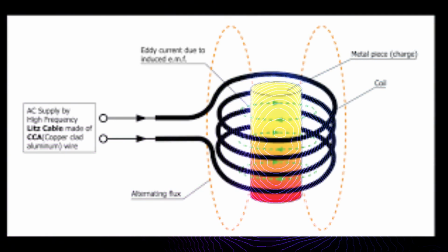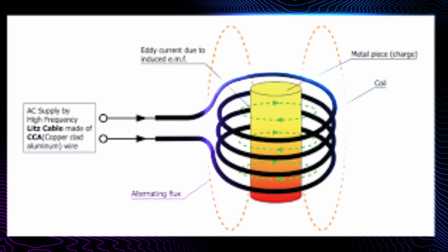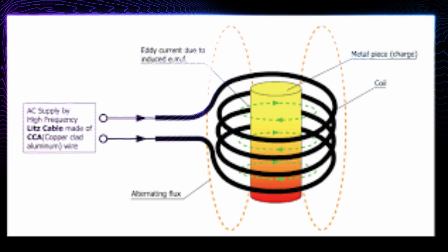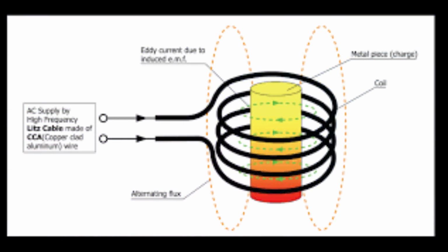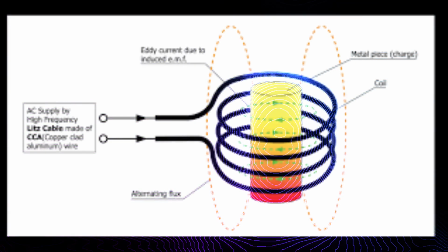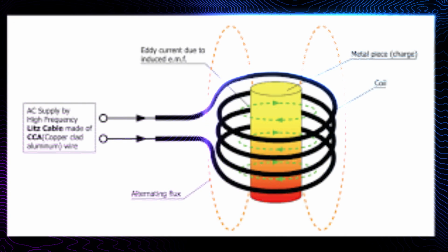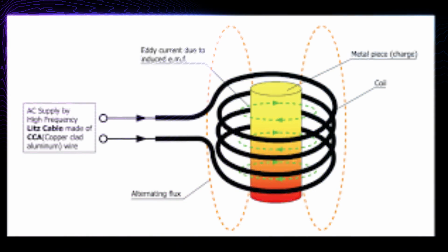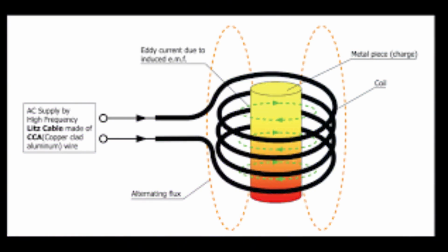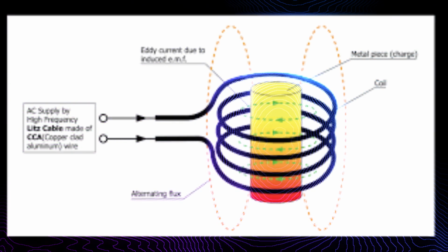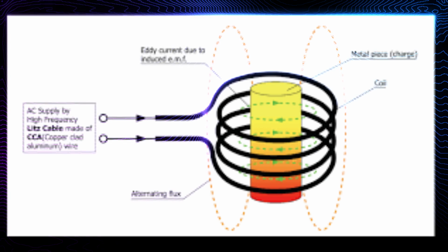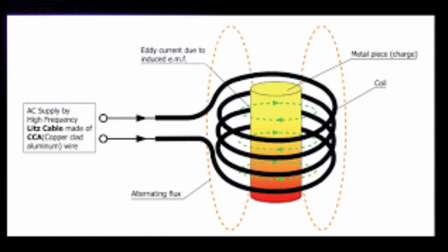This reactance is caused by inductance, so it is called inductive reactance, and is symbolized by XL, pronounced X sub L. Inductive reactance is measured in ohms, just as resistance is, and can be computed when the values of inductance and frequency are known.